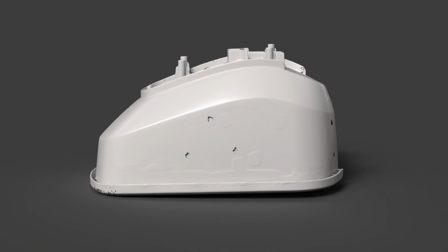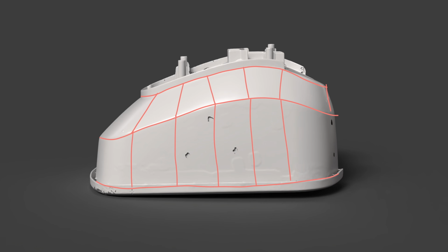So in this video, I'm going to use another approach. In most professional CAD software, you can create a surface patch. First, you need to be able to draw this 3D curve. It's going to curve in two directions. And then you make a cross rail to create a patch surface. After you stitch all the patches together, it will turn from surface into solid. Then you can hollow it to the required thickness.